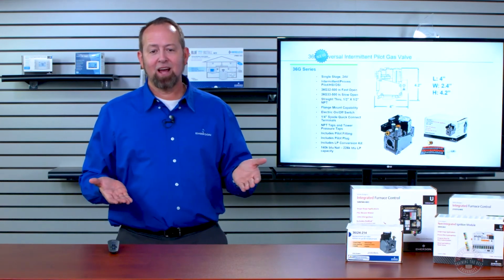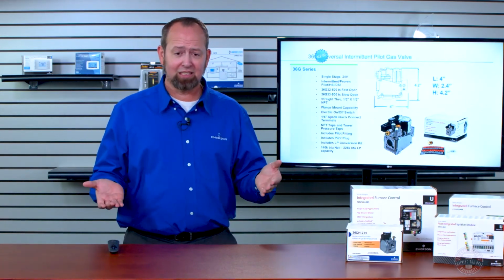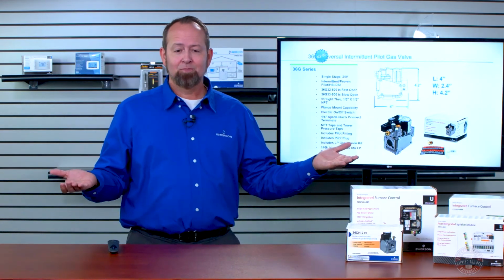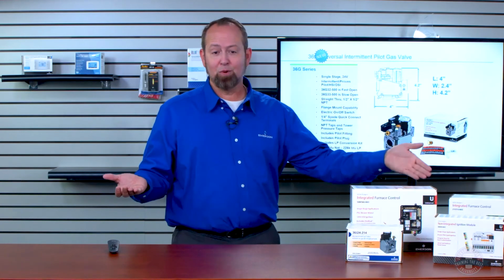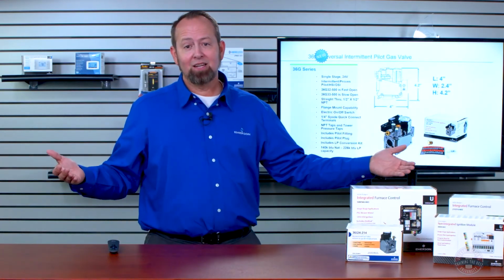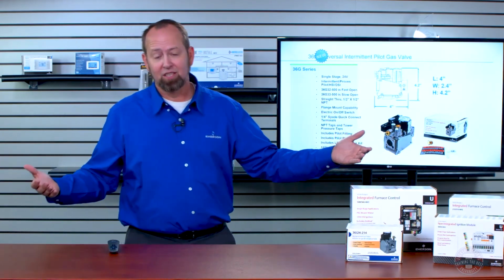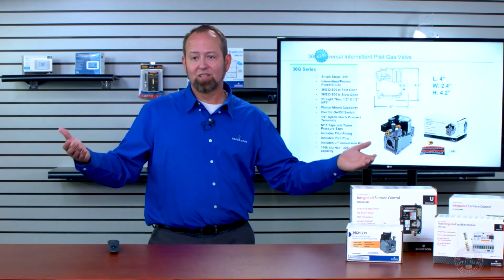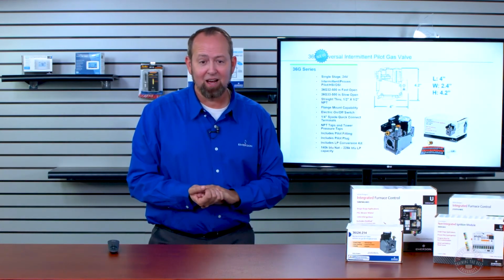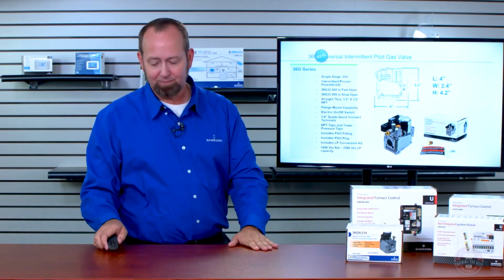Again, this valve on your truck is going to stock what you need. You can have a fast open and a slow open in this that's going to cover from the 2-burner, 50,000 BTU furnace all the way to the 125,000 BTU, the 5-burner furnace. And a lot of our furnaces are going to be somewhere in the middle of that. This valve will work in the majority of applications that way.